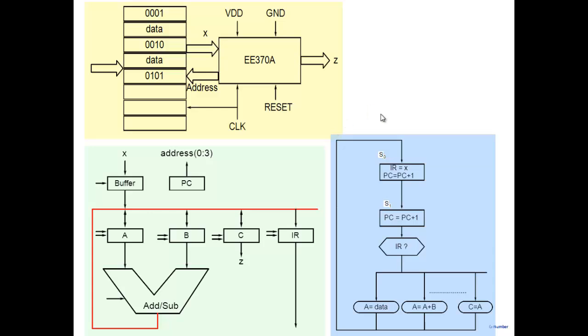So thereby, you can see that by adding a program counter, I'm now able to supply the address here and then read from an appropriate place here, from the memory. So this is a more general purpose system. And this is what my system goes through. S0, S1. When it goes from S0 to S1, it has to generate some control outputs here. And when it comes back from S1 to S0, depending on the instruction register contents, it has to generate some control outputs. Control outputs are all the inputs that you see here.